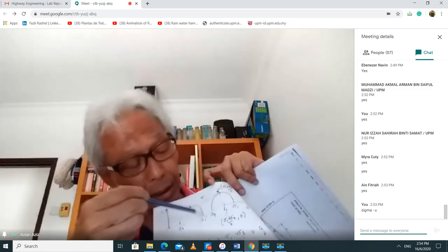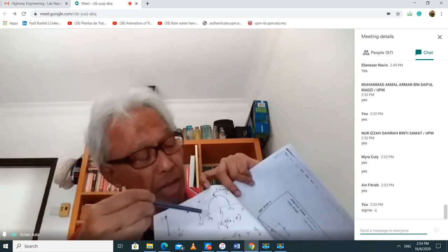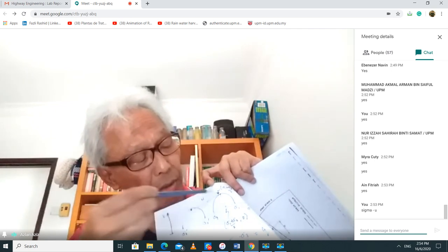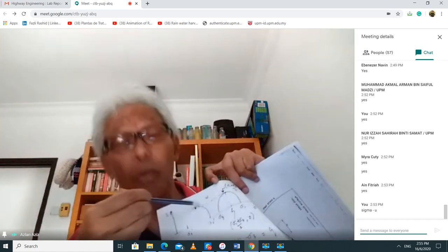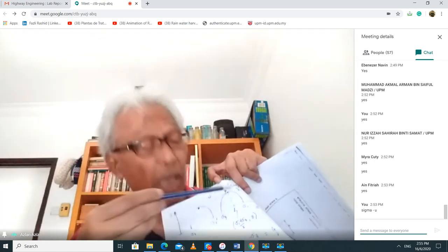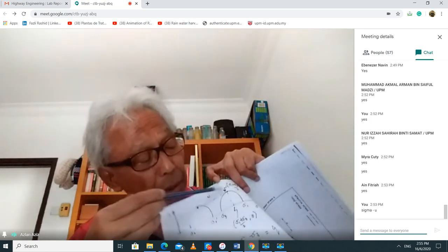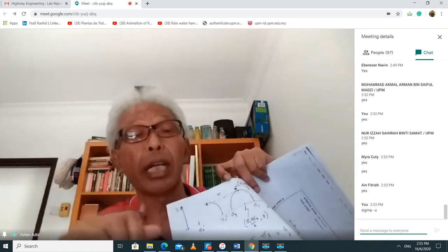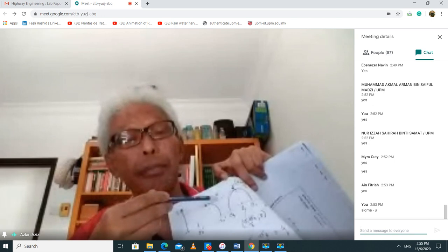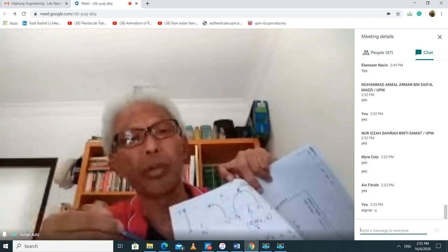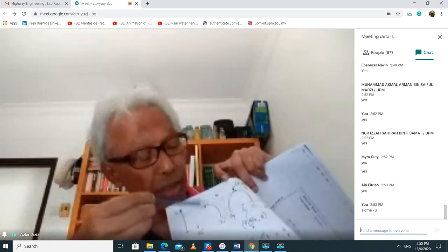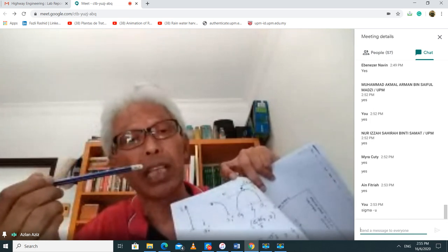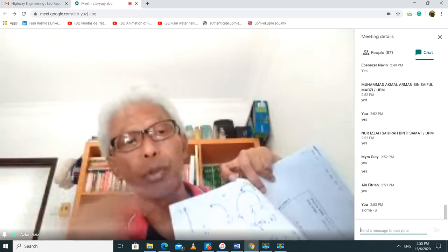I know he's awake now. This is the effective stress. This is the total stress Mohr circle. So they are going to be separated by only the pore water pressure U. And I'm just going to consider the top here, so it's easier to see. Okay, so this is the pore water pressure. All right, sigma prime is equal to sigma minus U. So this is always the case. Okay, this U is a constant.